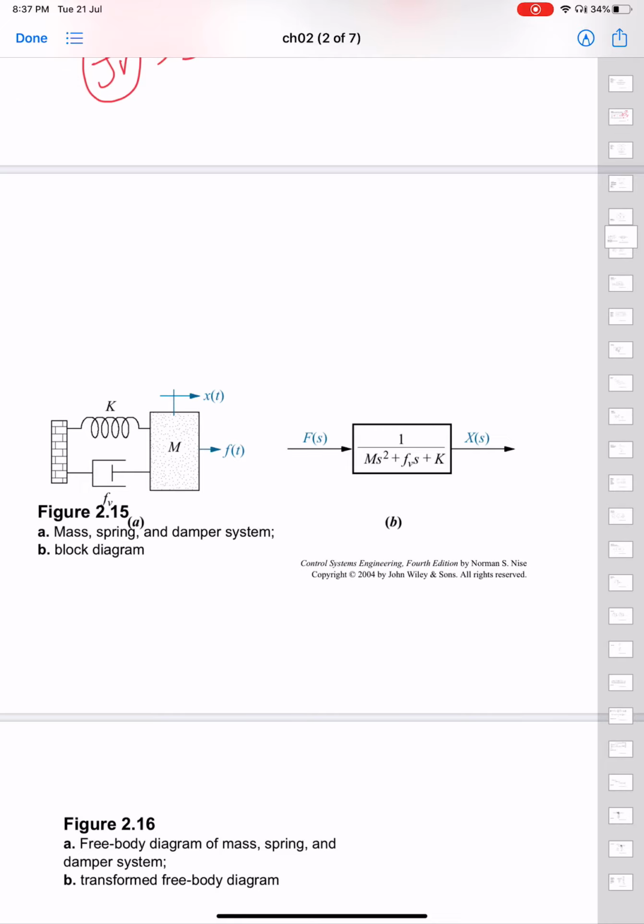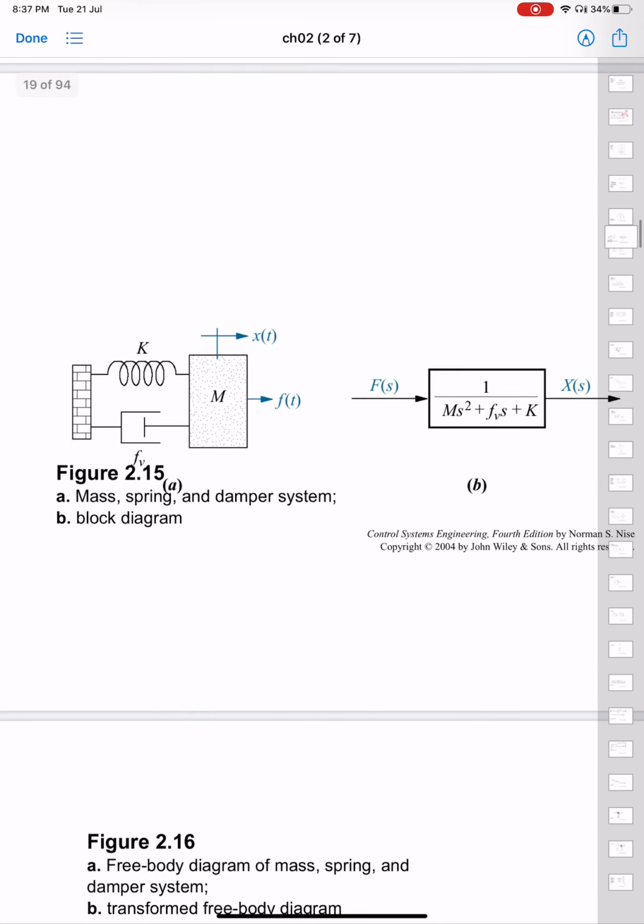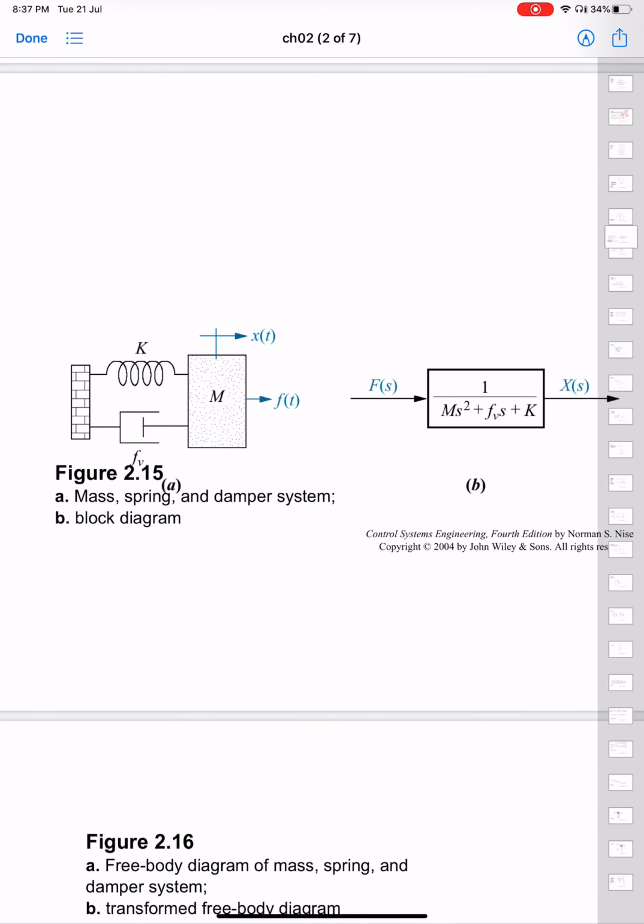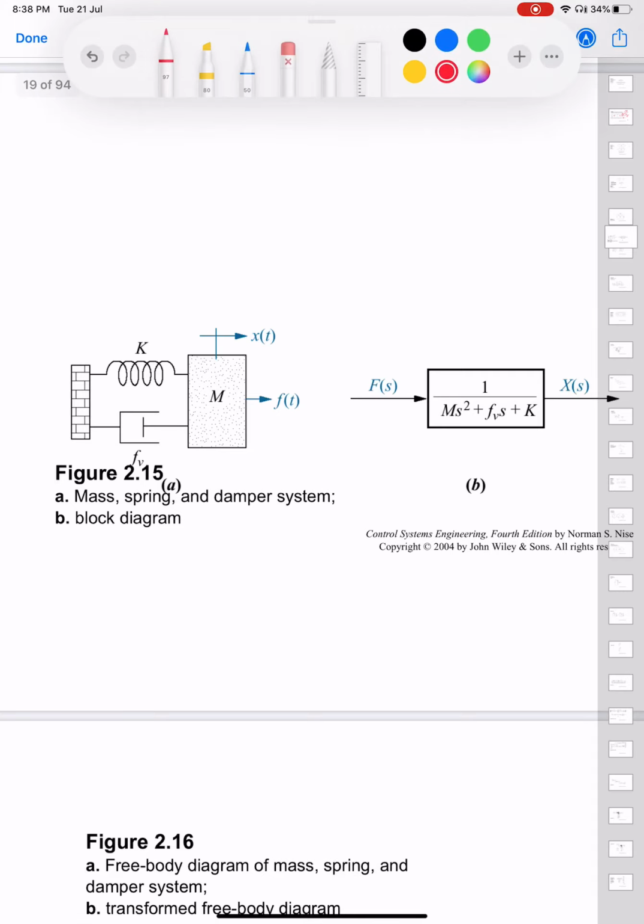So now you have a mass spring damper system here, for example. It is actually modeling something which has a mass, which has some spring characteristics, and which has some friction, right? It could be the model for any simple mechanical system which has translational motion. So you're applying a force here, and consequently, this mass, spring, and damper have to basically counter the three resistive forces, right, that you're applying.